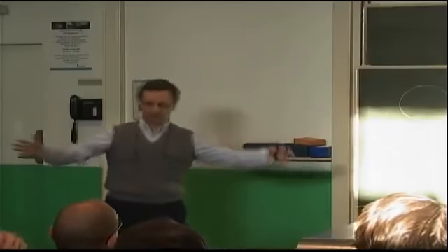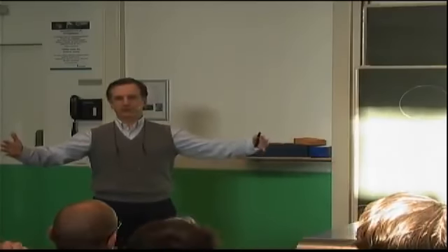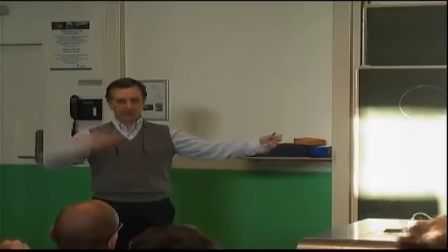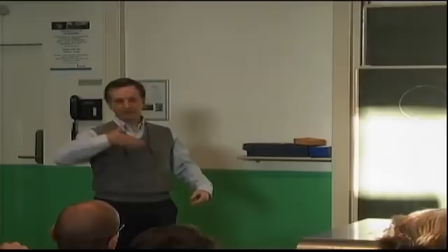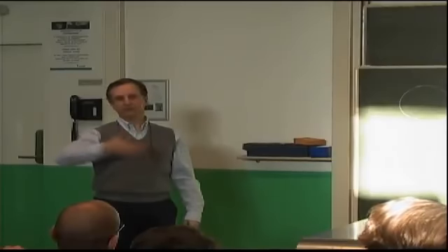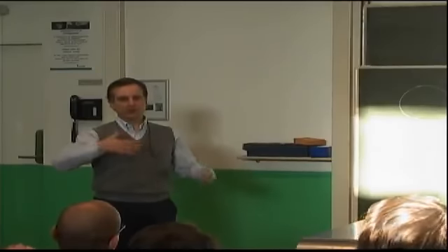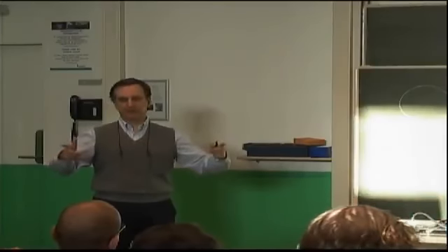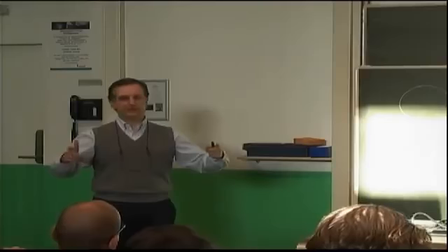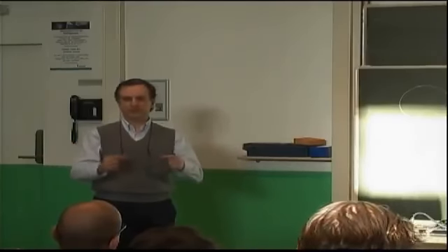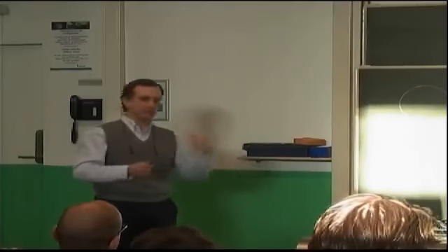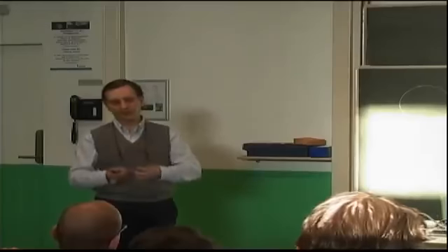Well, if each skin portion between frames is half a meter in length, and depending on where you put your stringers, you have stringers every 15 centimeters, let's say. So you can replace even a single bay, 15 centimeters by 50 centimeters, by this, and if you just put a strip of material in the middle to represent the middle layup, you are saving on the stringers and you are increasing the buckling load.